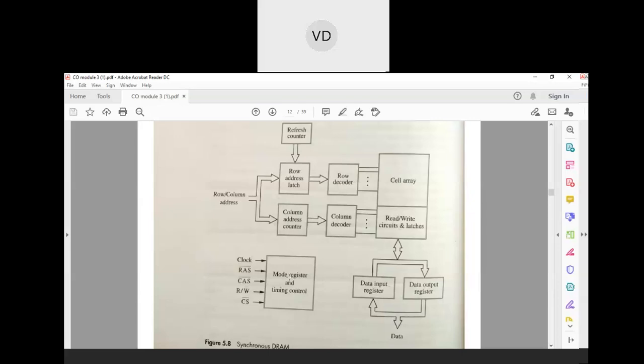Why we are doing this, we have already seen in direct memory access. If we transfer data word by word, then after every transfer of a word, an interrupt signal should be generated. But this will become hectic. To avoid this, we are going for transfer of a complete block. Direct memory access means a direct block of data is transferred from the memory to the processor, or processor to the memory, or including any device. So when the complete block is transferred, then one interrupt is generated. Because of that, we are going for complete block transfer.